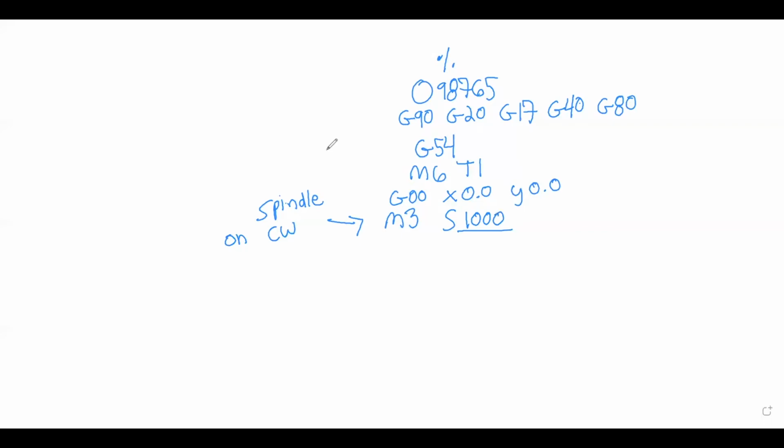After that, we now have to tell the tool a Z height offset. So we have told the machine an XY offset, and we now need to tell the machine a Z offset, and this will come in this line here. I spoke earlier about how the machine 0 is in that top right corner of the machine. If we're looking down at the machine, here's our work.